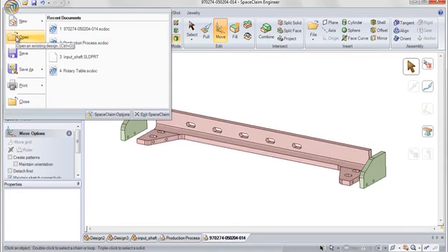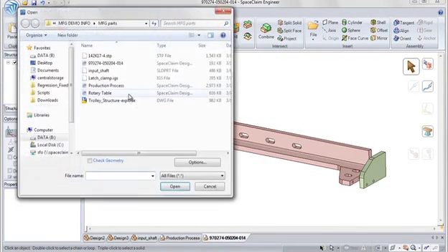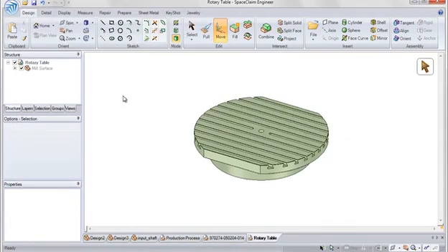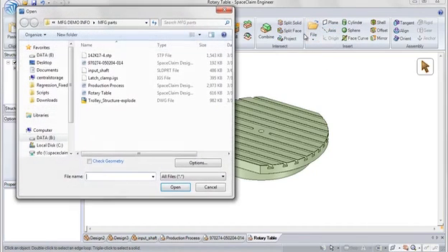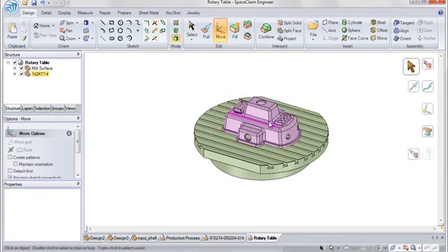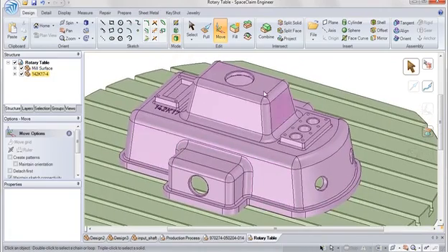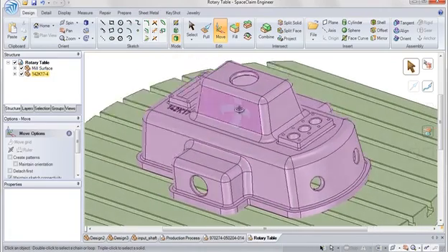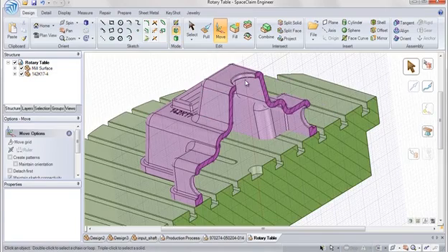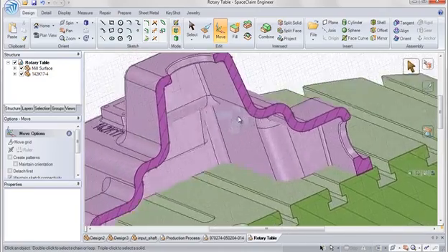Finally, in the manufacturing workflow, we can easily play around with the design. Maybe instead of initially trying to create this part that I'm bringing in as a molded part, maybe we want to machine this instead. So as I bring this in, you can see that the initial design of this part, when we were going to mold this, well, it has draft on it, a lot of rounds. Maybe we want to get rid of some of that. So if I go into a cross-section view, you can see that draft there on both sides.